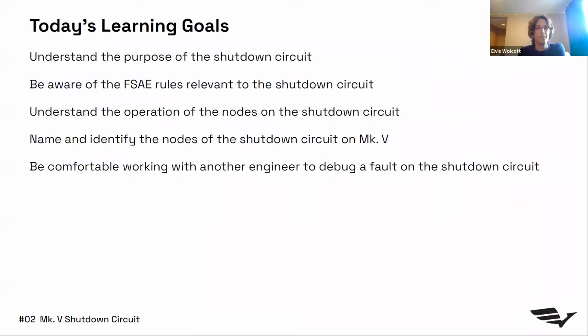Today's learning goals are that you should be able to understand the purpose of the shutdown circuit, be aware of the FSAE rules relevant to the shutdown circuit, understand the operation of the nodes on the shutdown circuit, name and identify the nodes of the shutdown circuit on Mark V, and be comfortable working with another engineer to debug a fault in the shutdown circuit.